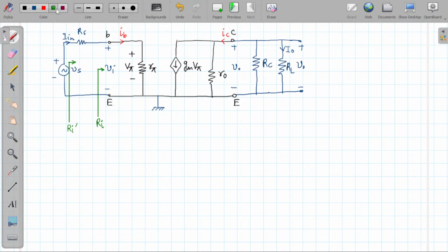Similarly, if we talk about the output impedance of the BJT, it will be here, and the output impedance of the total circuit can be calculated from this point R0. So now this is the model, and we have to find the different values. First of all, if we want to calculate the R pi value, R pi means beta AC divided by the GM value.